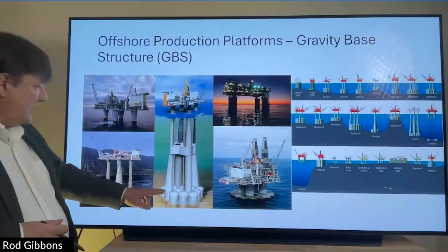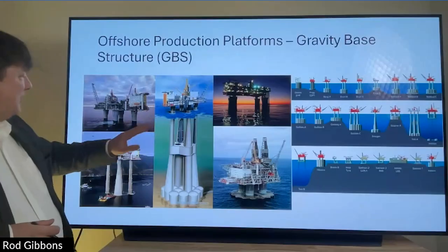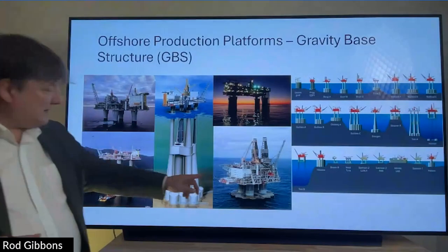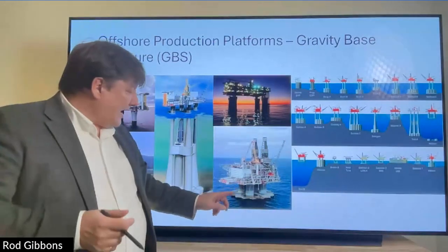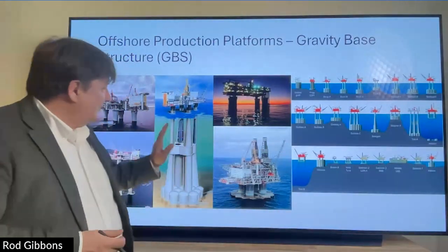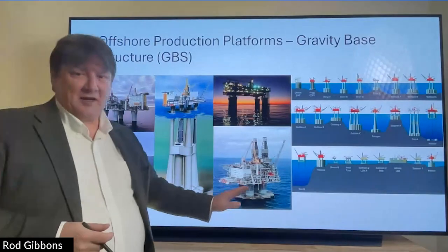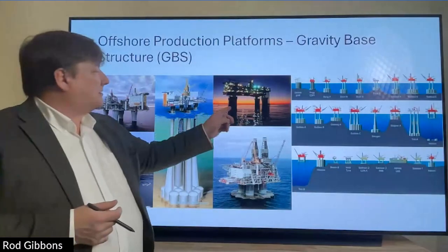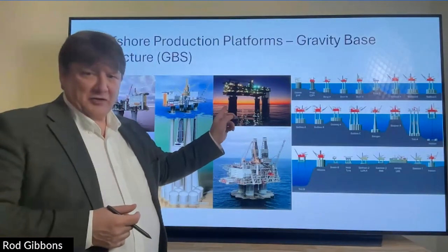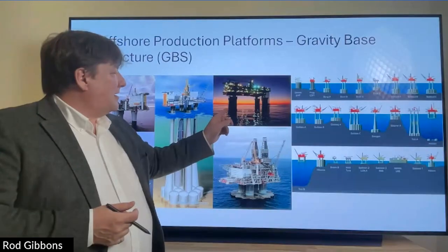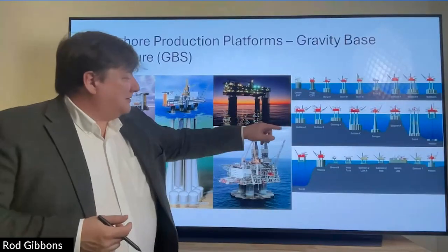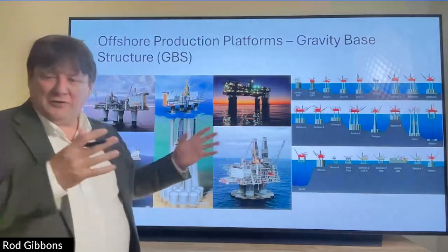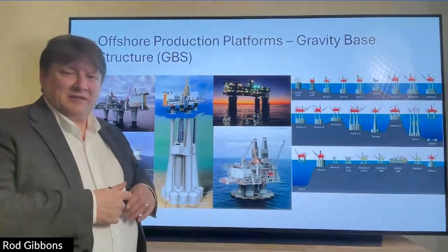It's concrete that's slip formed up, in cold water environments. So this is Norway, and this is Hibernia just offshore Canada. This large concrete structure resists ice, so it can resist ice loads. This is a gravity-based structure in Australia, and its primary purpose, the gravity base, I don't think it's in these diagrams, is for oil storage. The concrete is hollow, and you can use it for oil storage.